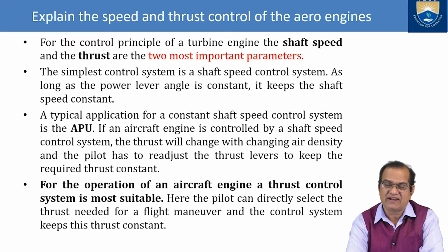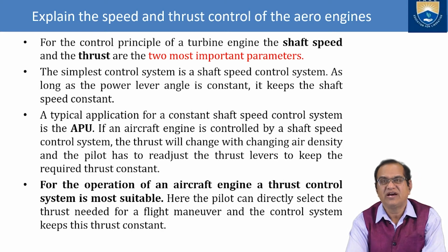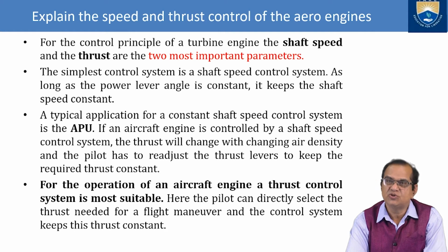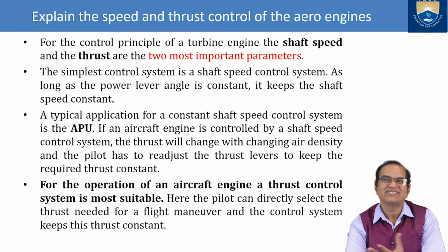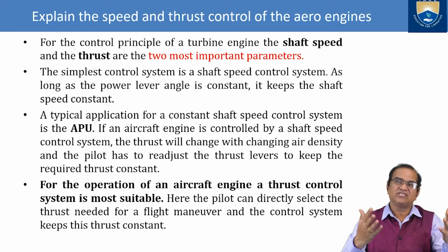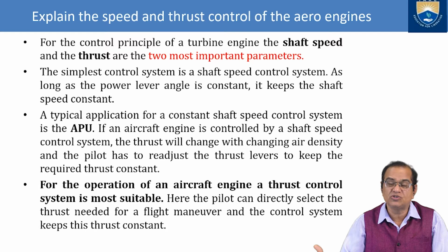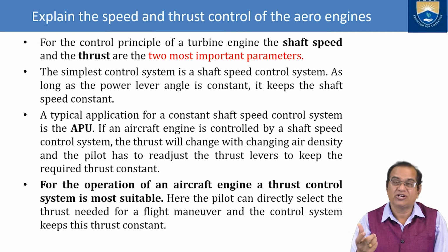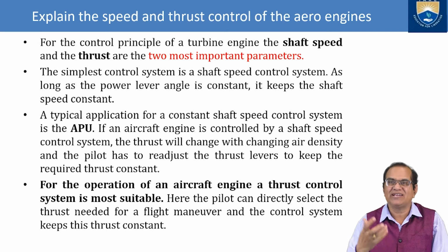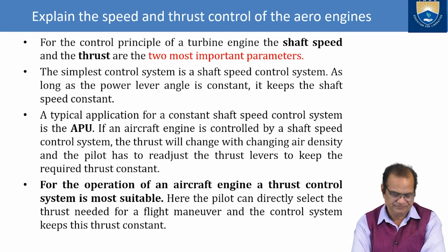Like a propeller aircraft, when you go to high altitude, the density of the air is reduced. So from the same speed, you cannot get the same thrust, because it is dependent upon the mass of the air. If the density is reduced, the mass is reduced, so you need to operate more throttle. So the speed of the propeller will increase, and more quantity of air will be sucked.